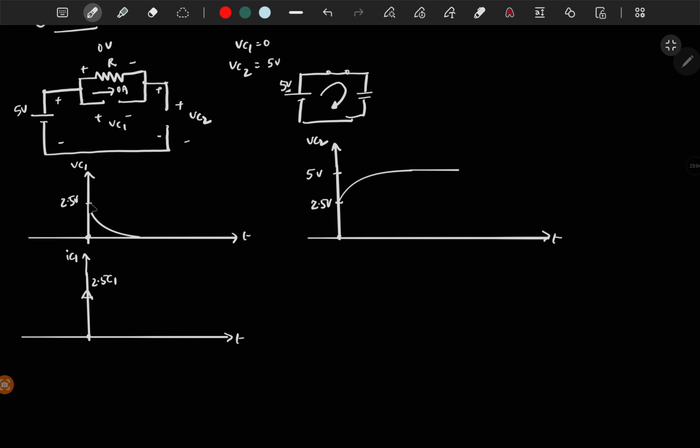And also the voltage across the capacitor C1 is discharging exponentially. So if you remember, for a capacitor we generally represent the current in this direction, right? If there is some voltage, but this voltage is decreasing exponentially, it means the capacitor starts discharging, right? It means there should be current flow in this direction. The current should come out of the capacitor, then only the voltage across the capacitor will decrease, and then it will decrease to 0. So from this we can say the current IC1 through the capacitor is negative because it is discharging.